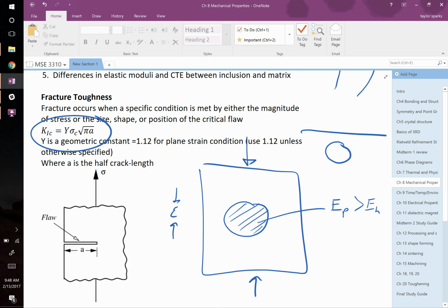Well, you can take an example like this where you have a flaw in your material, and if you know the fracture toughness, and you know the size of this flaw, you can calculate what stress this thing will break at, right? When you look up a spec sheet, it says the yield strength of this alloy is 500 MPa or 200 MPa. That's just not a very good metric because that doesn't take into account any of the flaws that are present or how your flaws might emerge in the material. It's just saying as we make it, we find that it breaks around this level, right? Okay? So this is great.